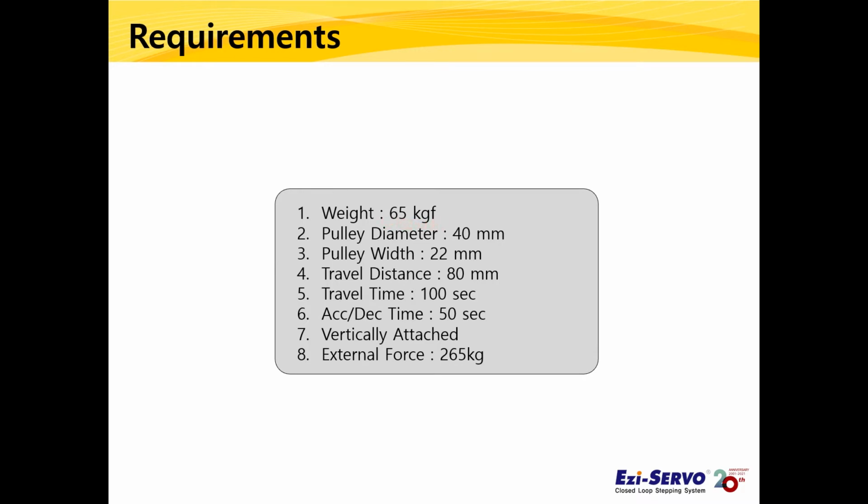The weight is 65 kilograms. The pulley diameter is 40 millimeters. Width is 22 millimeters. Travel distance and time are 80 millimeters and 100 seconds. Acceleration and deceleration time is 50 seconds. The system is vertically attached and works as a Z-axis. The external force is 265 kilograms.